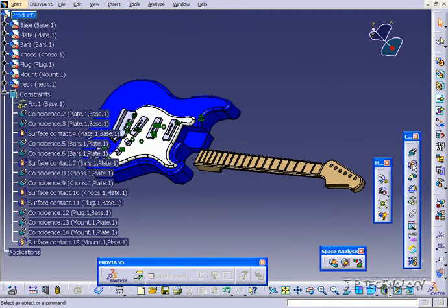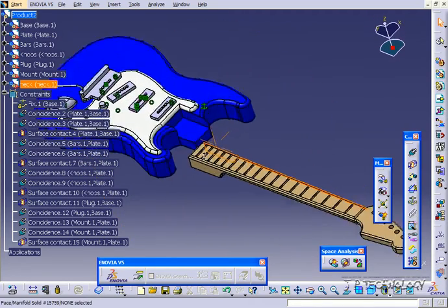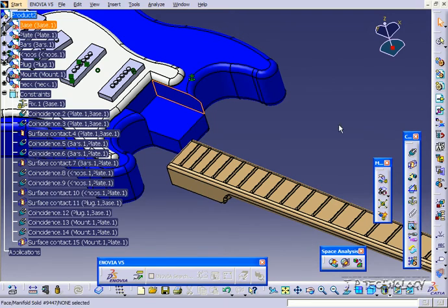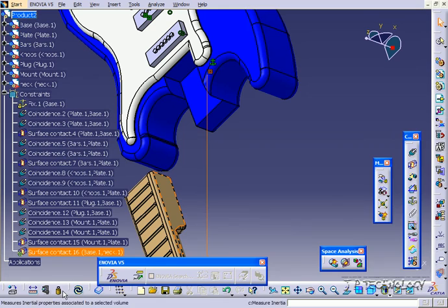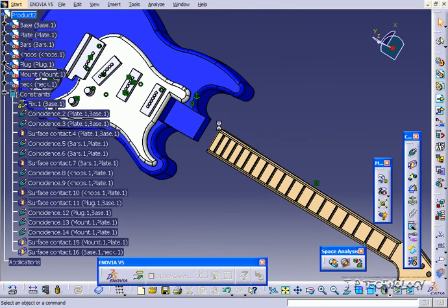And now let's mate this neck. So let's click contact constraint, click this face here, and click this face here. So contact that face and that face. Click update. Now once you make it, I want you to delete it just because of the geometry with this guitar. To position it in the place I want, I need to make a contact constraint here and then delete it so it kind of remembers, and then put the other ones in. If not, it's going to create a few errors.